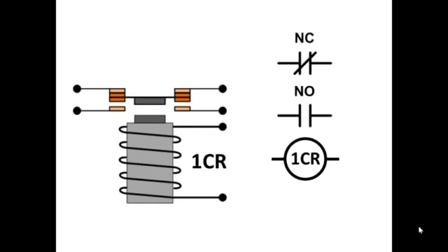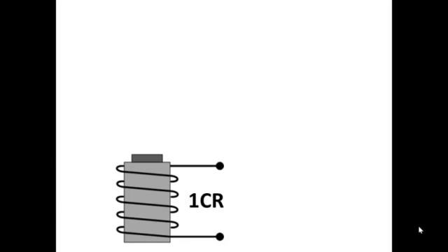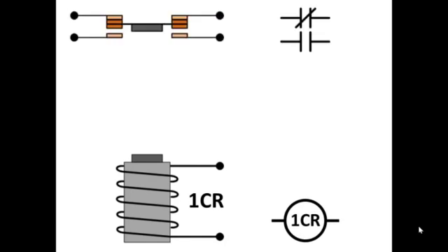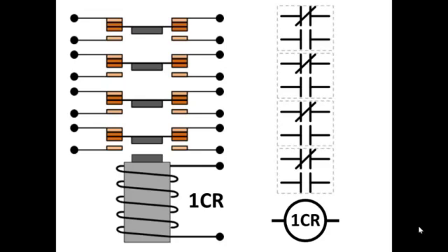With this newer design, the shorting bar design, the normally closed and normally open contacts are completely isolated electrically from each other. Once again, our relay coil, our symbol, if we need more than 1 set of contacts, 1 normally open, 1 normally closed, we simply add them in the stack. Of course, it's going to take a stronger spring and a more powerful electromagnet to move the additional mass and move the heavier spring. But notice now the symbols for our contacts. We have 8 separate symbols, not 4 sets of 2 symbols, but 8 separate.